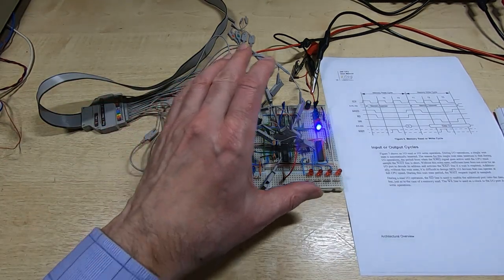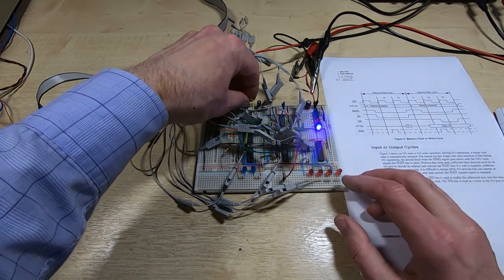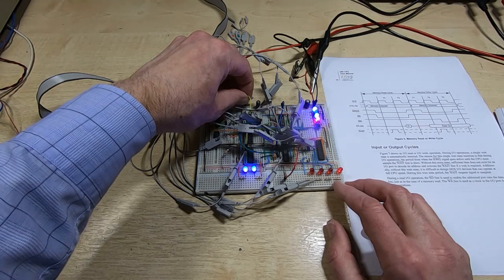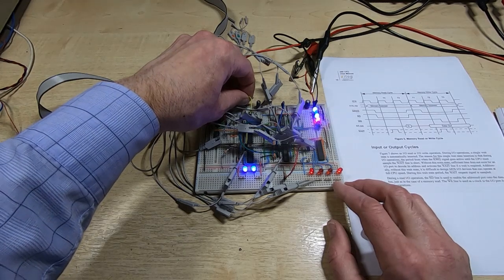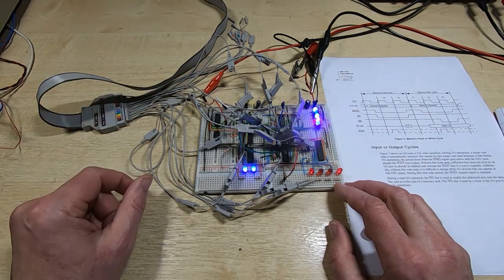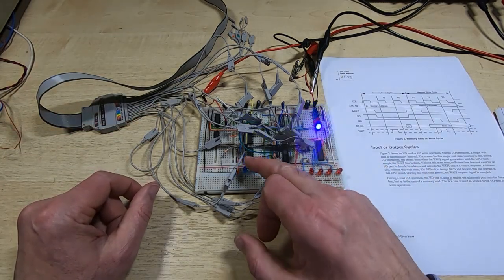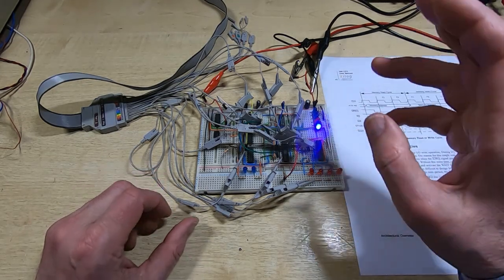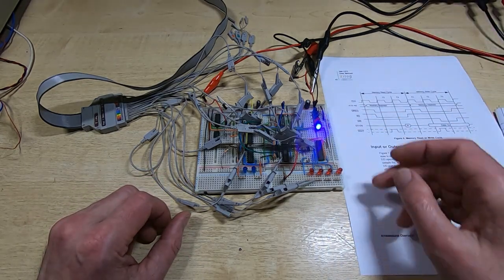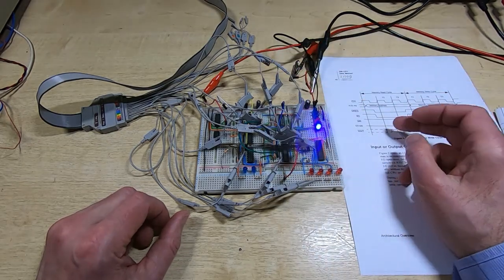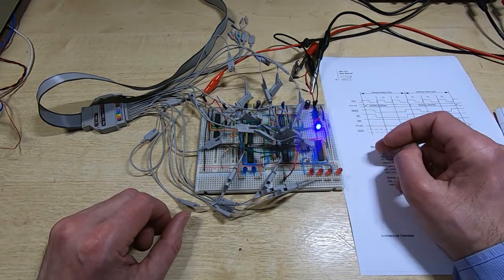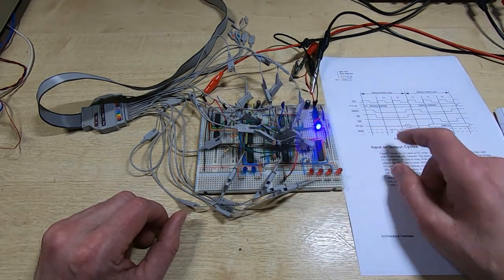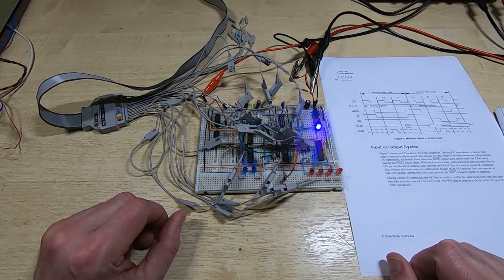Okay, so the LEDs won't make that much sense. One other thing I'll just point out is the two LEDs down here. Notice that they both come on when the cycle starts, because we are forcing the floppy drive controller to give us access to the data register. Okay, so what I'll do now is move the camera so you can see the logic analyzer. I'll change the clock coming in to maybe a hertz just to speed things up a little bit, and then we'll look at a couple of cycles and see if the cycles match what we need the system to do.